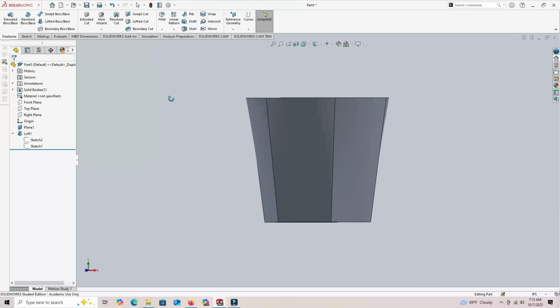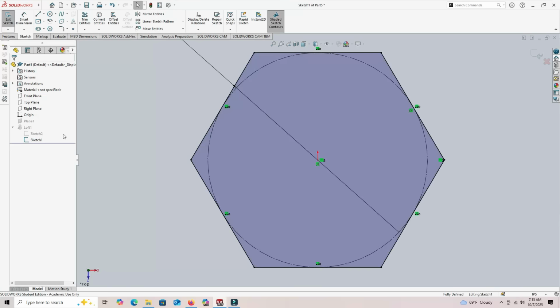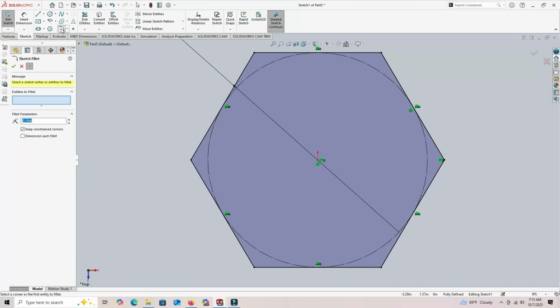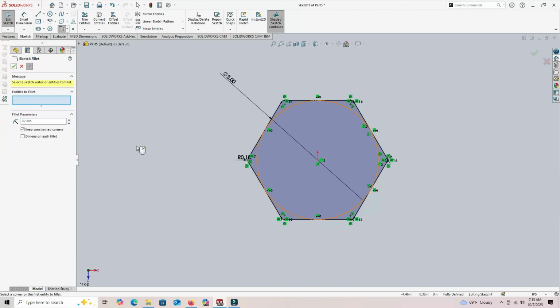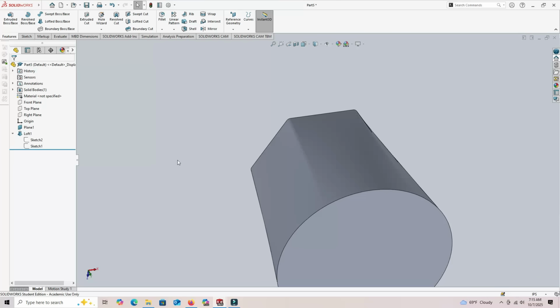And yeah, I'm gonna go ahead and edit sketch 1, and I'm gonna add some little fillets in the corners of the hex, and I bet you that's gonna soften things up pretty nicely. Yeah, we'll stick with that. We'll see how that looks. And I'm going to choose those corners here, all 6 corners of the hex. Let's exit the sketch. Oh, look at that.